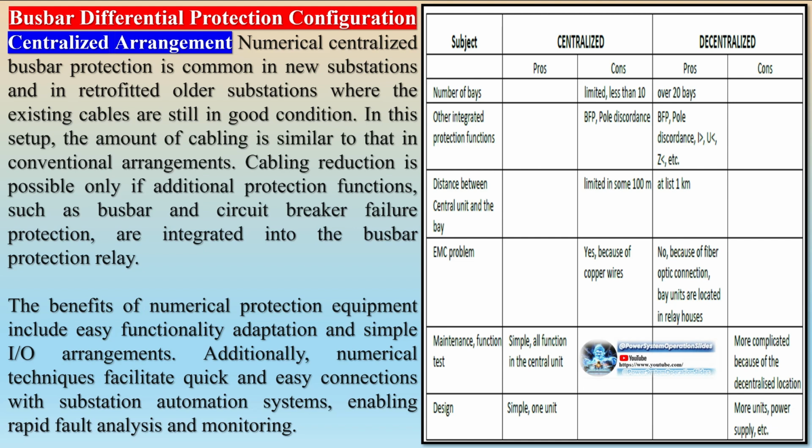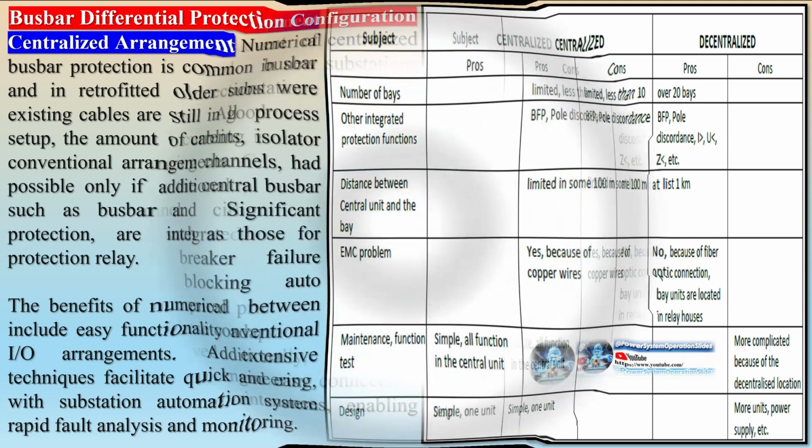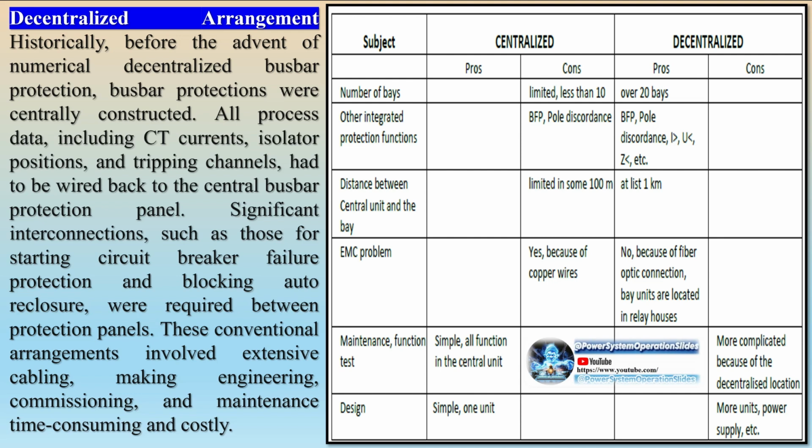Busbar protection blocking scheme. Supervision or blocking criteria. The absence of differential busbar protection in a substation can significantly impact the stability of nearby power plant units. Ensuring operational reliability during a short circuit is crucial, as losing an entire substation due to busbar protection failure is unacceptable. Therefore, real-time monitoring of busbar protection functionality is essential.